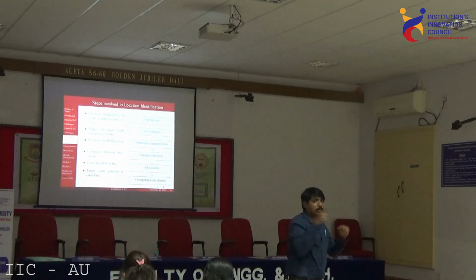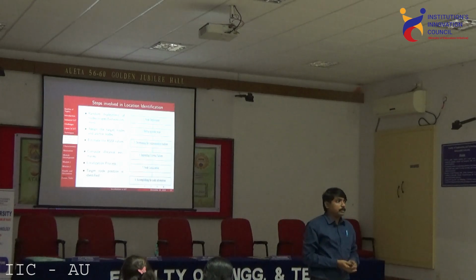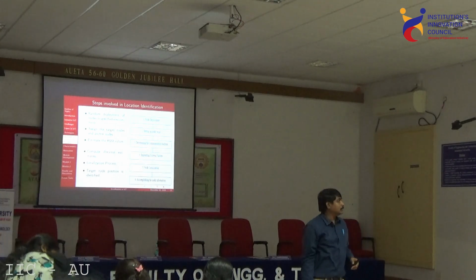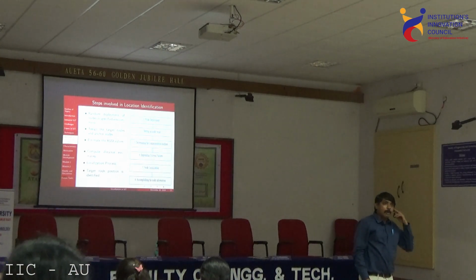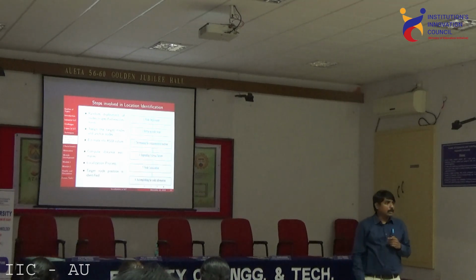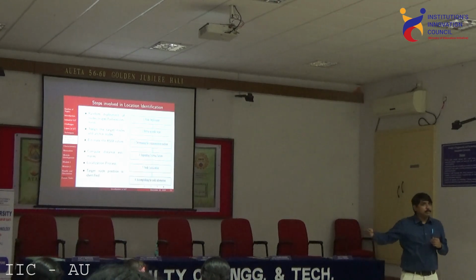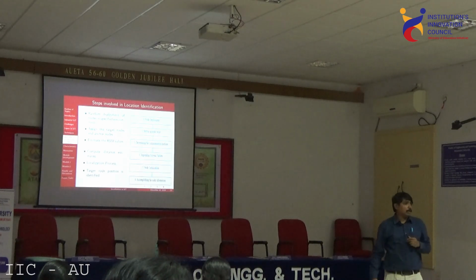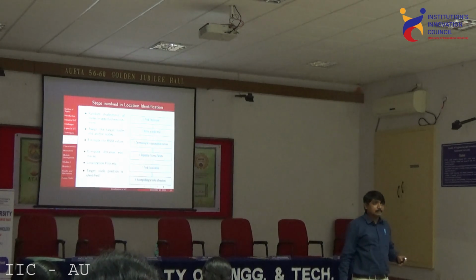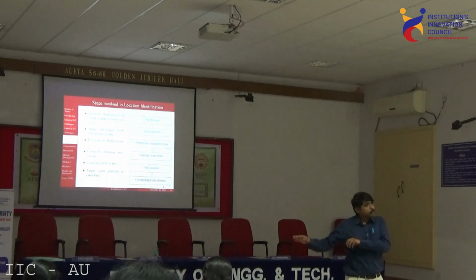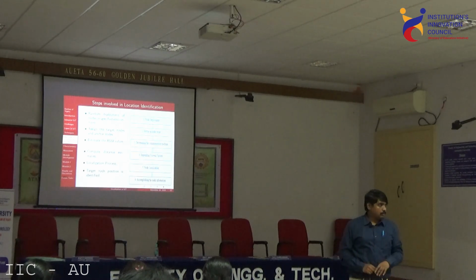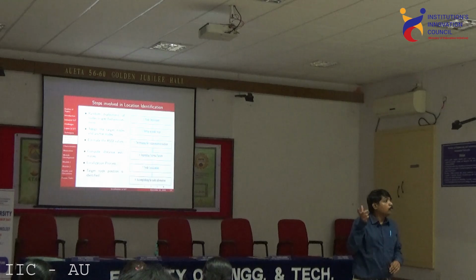If I am trying to find all the reference points, all the reference points should be within the communication range of a particular node. That's what is happening, right? Let us say I want to communicate with my Bluetooth headset. I may keep my phone over there. Up to 10 to 15 meters, I can get the signal without any loss. If I go beyond 15 meters, surely there would be a data drop. If I go past this door, then I will not hear what is happening. That is the communication range of Bluetooth.